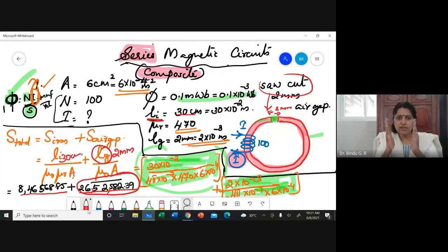But the problem is that when you have small, thin slices stacked together to form a core, that is how in a transformer you have a core. They are stacked very close to each other and bolted very close to each other so that no amount of air gap comes in. Even a small air gap of 1 mm or 2 mm will become very costly for you because it provides a large reluctance to the path of the air gap.